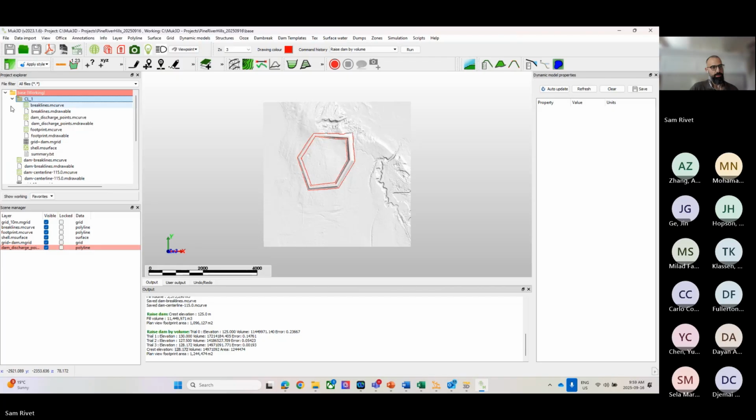Once again, and maybe there's something to be careful of, because I had the same base working directory, and I've defaulted this to save automatically every time, it created a new CL1 folder and repopulated all those layers. So it saved over what I had before. So that's something to remember. It's going to save automatically, and it's going to name it the same way, and it's not going to ask you if you want to overwrite these files. It's just going to save it. So if you're going through different scenarios and you want to keep old structures that you built, maybe move your working directory around or create new subfolders before you run the template again.